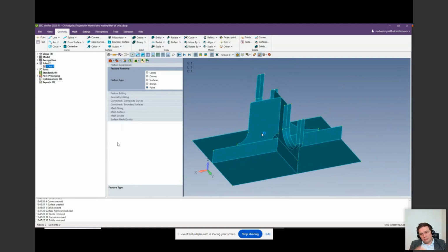There is also a mid-surfacing capability, which is completely automatic. What you basically do, you import a STEP file and automatically define the mid planes, which remembers the mesh thickness, the solid thickness, to assign that to the mesh attributes to be able to represent that when meshing.